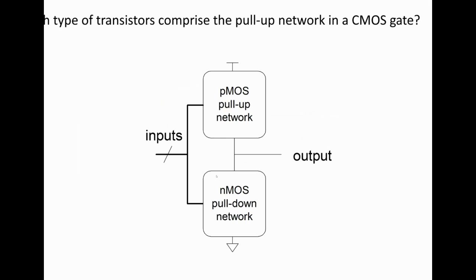If you think of transistors as switches, but as we saw, if you look at a curve where you plot the V out as a function of V in, there is a point in the middle where technically both the pull up and the pull down are turned on, but turned on in that region usually means they're saturated.